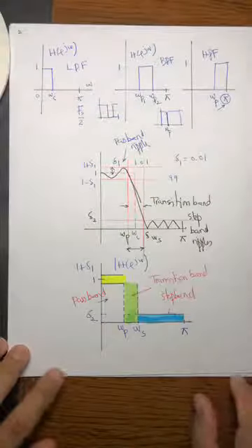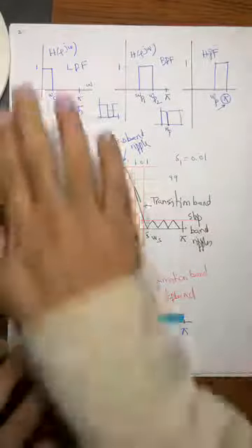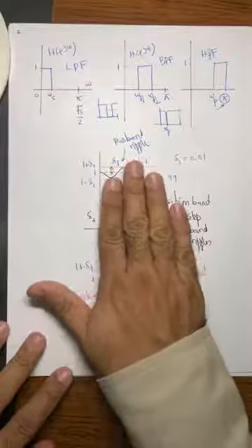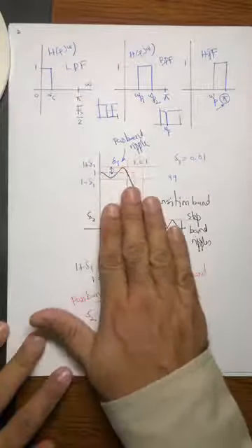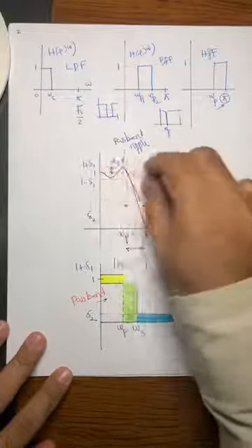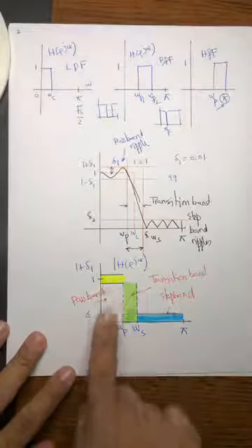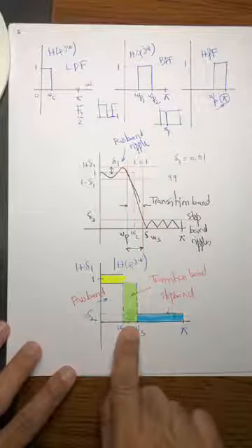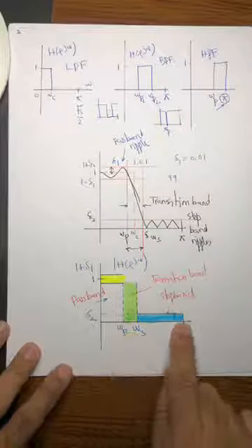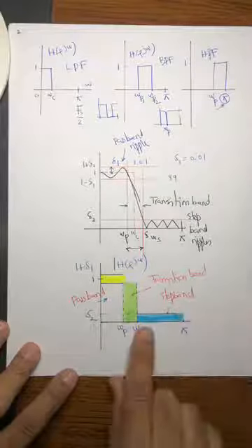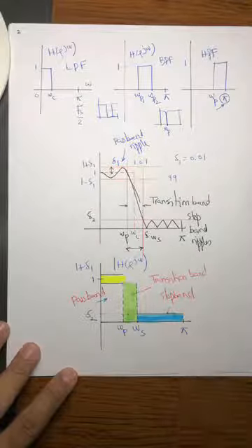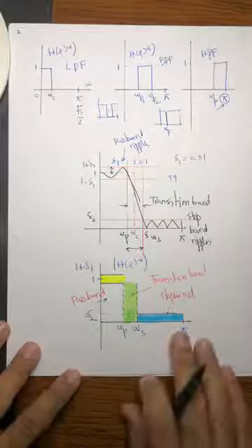You are to design a filter. You cannot design an ideal filter, so you have to live with something realistic, and something realistic requires a little tolerance. You have to give a little tolerance for the frequency response in the pass band, this yellow region, and a little tolerance in the transition band, as it cannot just drop down to zero, and a little space to live in the stop band. It cannot remain zero. There is absolutely no way for the frequency response to do that.